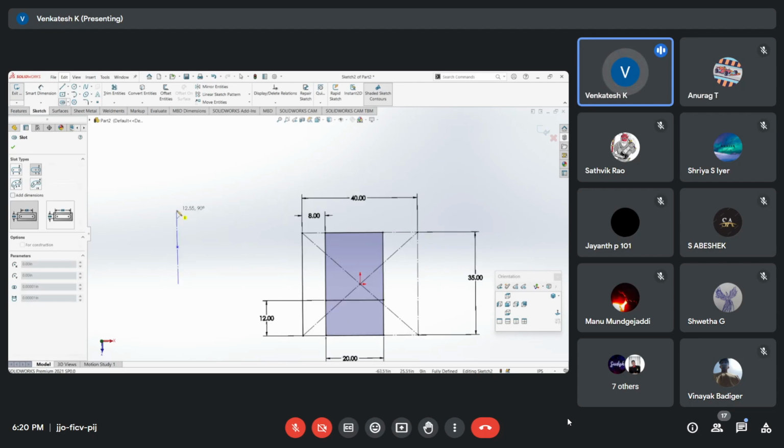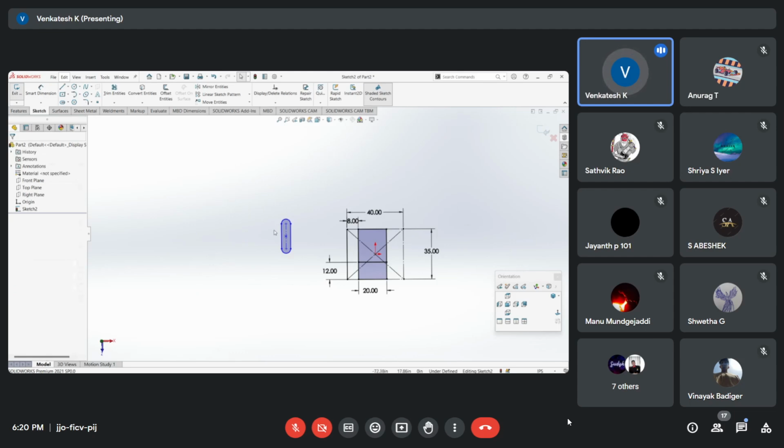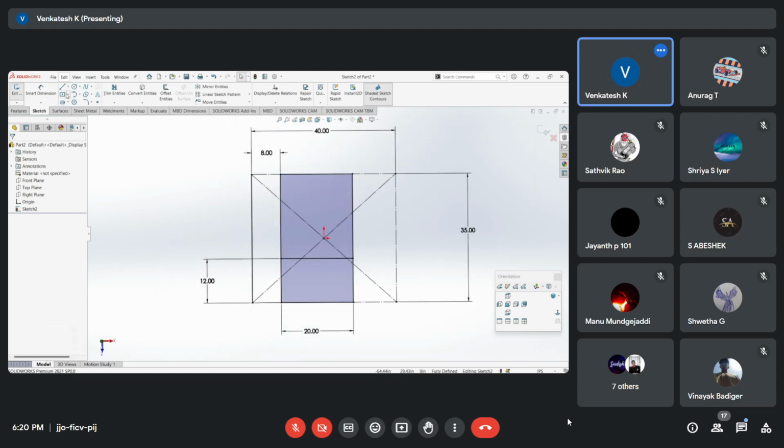You would have seen in many mounts, they normally don't give just a circle such that the screw fits. They give slots like this so that you can adjust it. You can move it vertically up or down or even horizontally, so that the motor or anything you want to mount can be put accurately. I'll be using underline for a structural member.